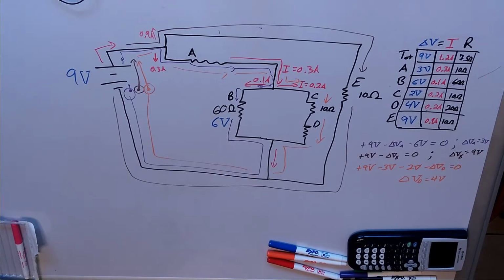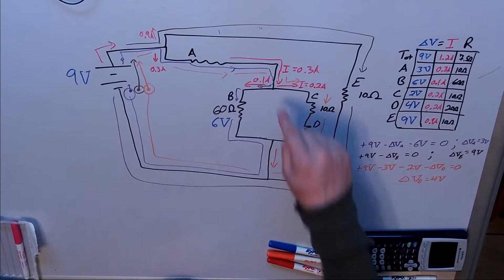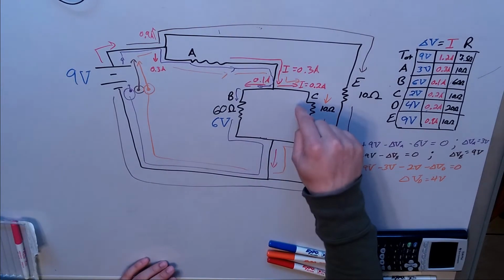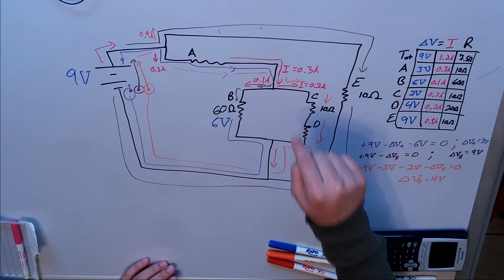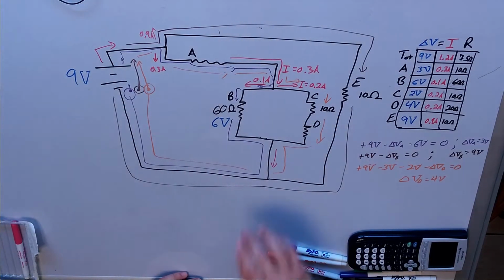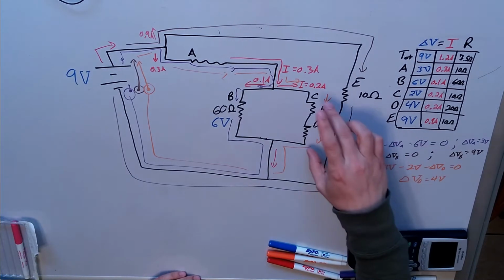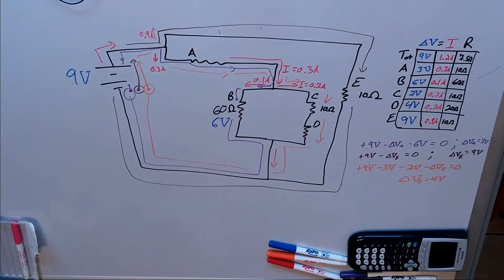Now, you may have seen in some of the other videos where I've talked about it, "path of least resistance" is misleading because it makes it sound like everything's going to go through just the simplest path, which is not true. It will actually split itself up. Since twice as much goes this way, it means that this must have half the resistance. Well, this side has a resistance of 60 ohms. This is 10 plus 20. This side has 30 ohms. It does match what we would expect.